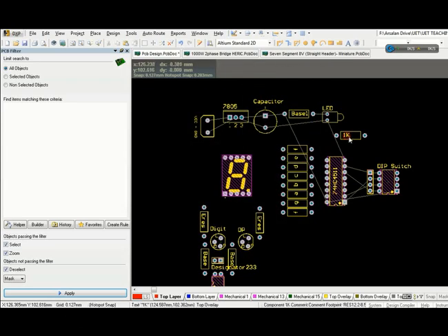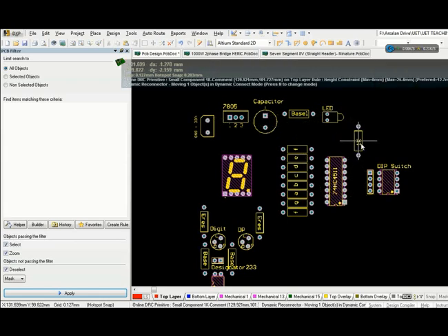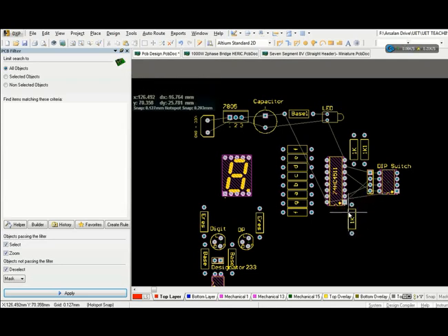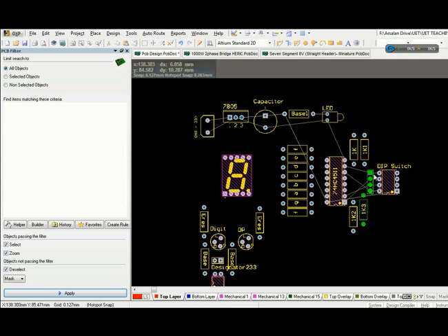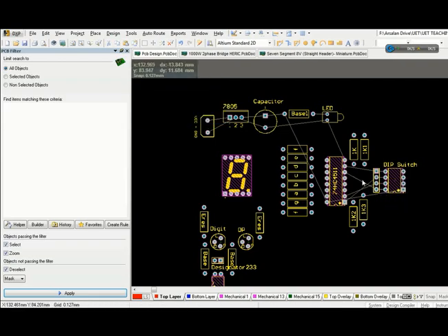So this is the 1 kilo ohm resistance which we have to add, which I have added also on the dip switch. So just see this 1 kilo ohm resistance, how I am adding this one over here. This is a very important resistance. If you don't add this resistance, you are not providing a zero ground path to the A, B, C, D or D0, D1, D2 and D3 pins over there.